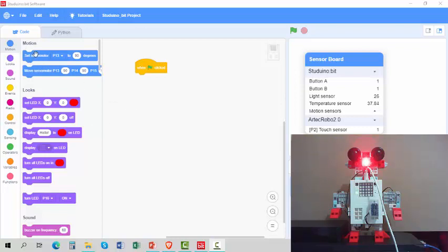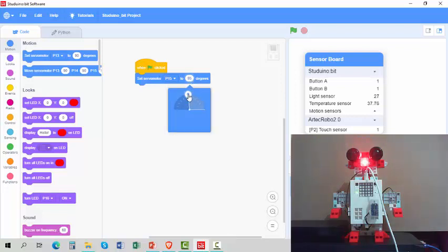Okay, so we need to set servos, but we are not writing the program at the moment, guys. We are figuring out what the limits are. That's setting the servo. So our first servo setting, I'm going to set there, and let's look at the head. That is for 13, that's for the arm. Let's go for 15, that's for the head. And there you see it moves, so let's put it to the right position. I want it right there. That is straight front, straight forward.